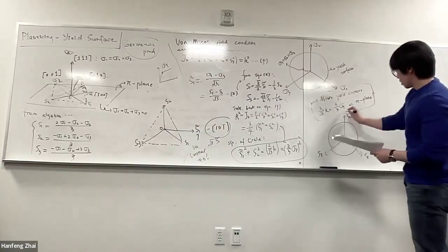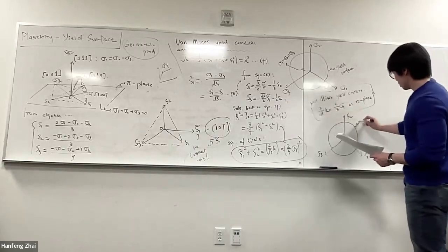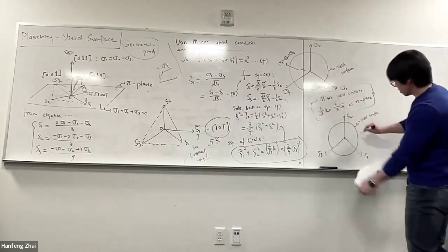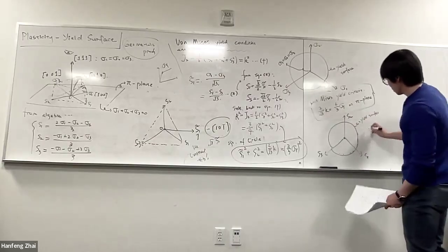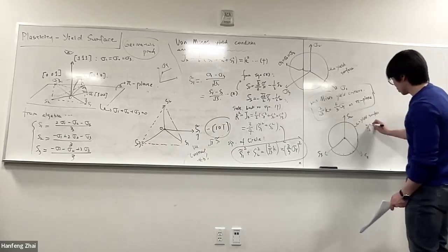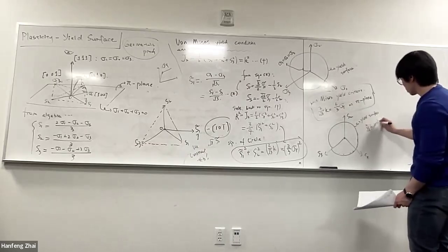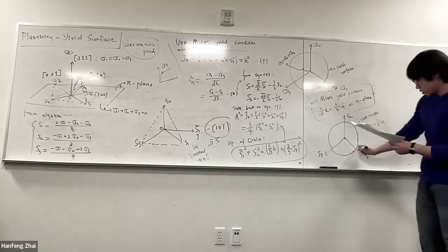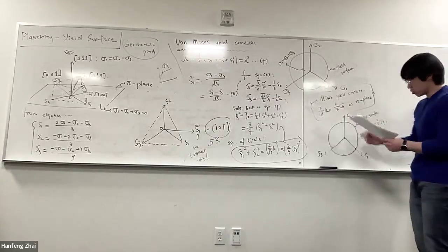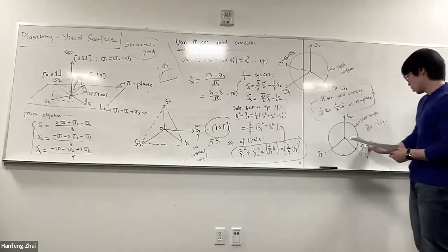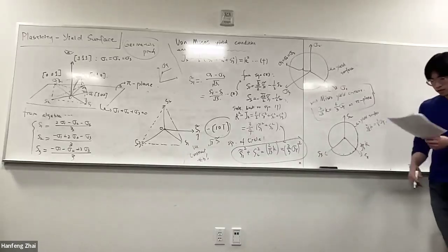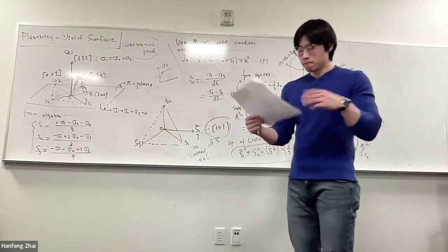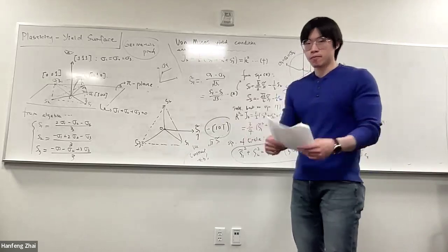And on the surface, because this is the yield surface, all the points that lie on the surface satisfy 2/√3 k equals 2/3 yield stress, which is the von Mises yield criteria. And then the radius is literally 2/√3 k. Okay, nice. So this is the general construction of the von Mises yield criteria in 3D.